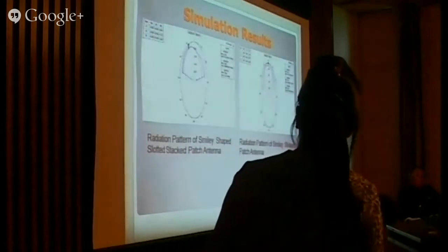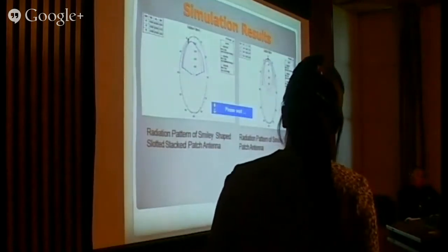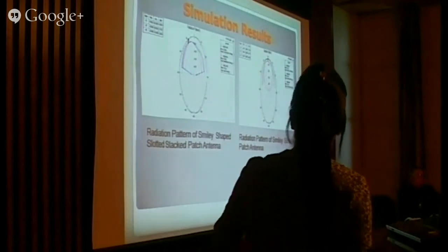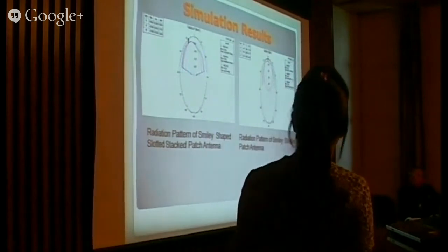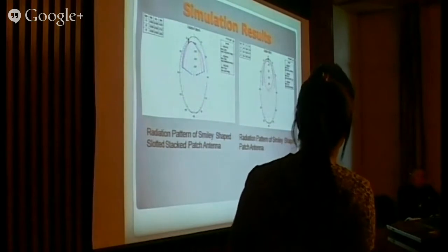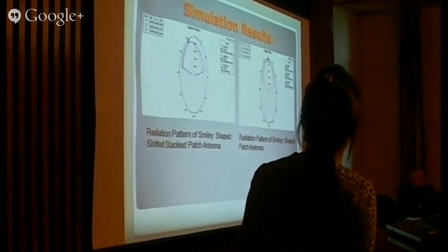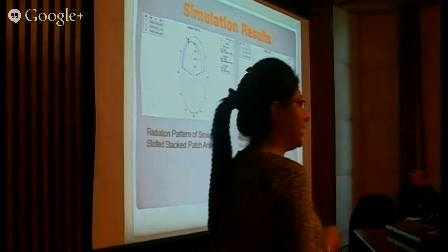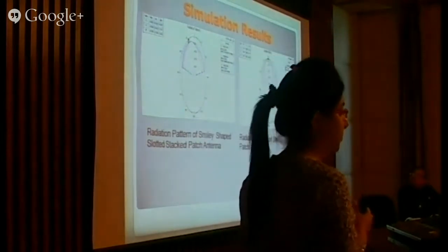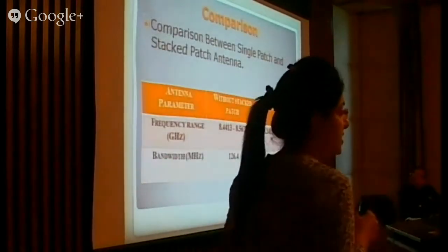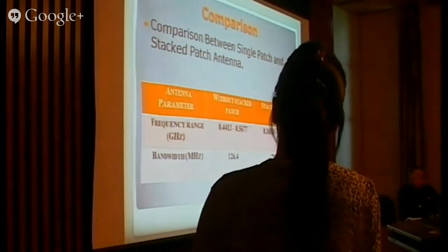This is simulated results. This result shows that the gain at resonant frequency without stacking is 5.7 and with stacking is 5.9. When we do stacking, bandwidth can increase but gain remains the same. This is a comparison between single patch and stacked patch.